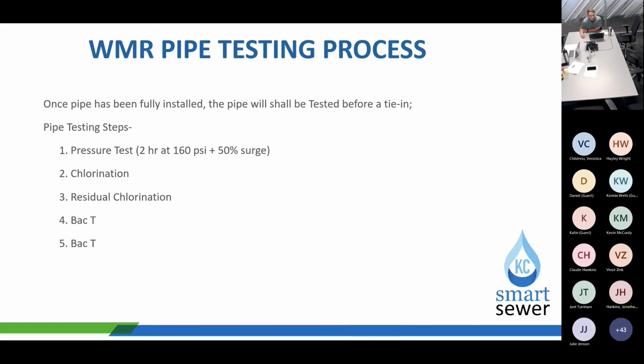Okay, so for testing, you have a hydrostatic test, which is also known as a pressure test. This test is a 2-hour-long test. Usually you have a stopwatch, be watching it. Usually within the first 10 minutes, you'll find out real fast whether or not this pressure test will last the 2 hours or not. So you'll have 160 PSI.